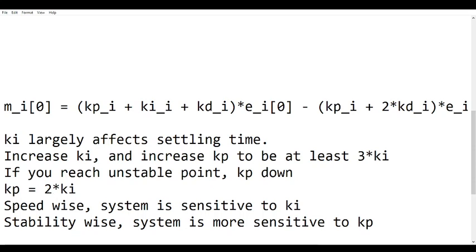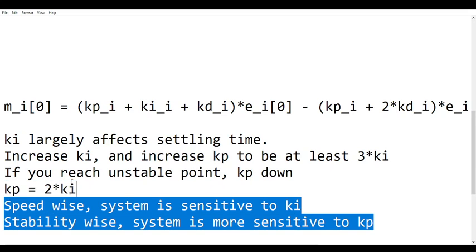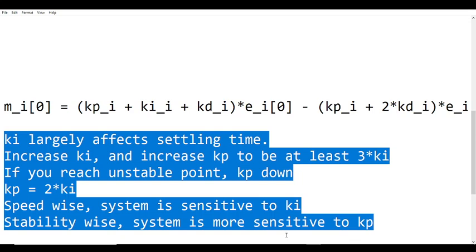It's gonna be closer, I guess, because you want your KI to be much bigger. You want the system to be kind of crazy. You want the disturbance response to be off the charts, to be very sensitive to disturbance and be able to react very fast to disturbances. But this is not a super dynamic system like a power factor correction. This is just DC-DC, so try to keep it stable. So anyway, I think this is better than the one I have there.